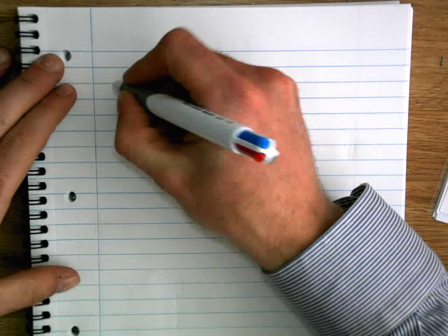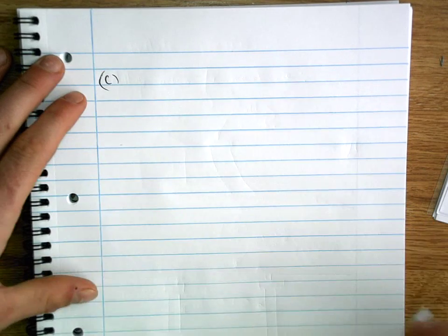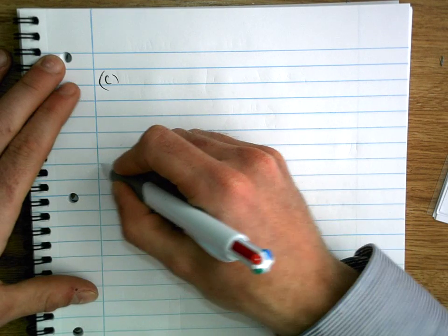So a more valid kind of an idea for underground pipework once it's covered would be to fill it up with water and then leave it for a period of time and go back and measure has any of the water escaped. Then you would know if there's a leak somewhere that it's leaking water, so obviously there's a problem there. So in order to actually sketch that out, so this is for part C, what I do is just do a cross section of the start of our pipe work.